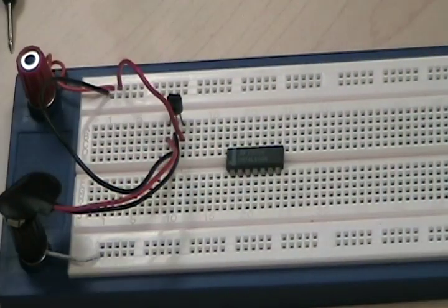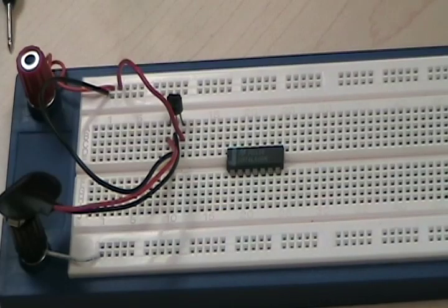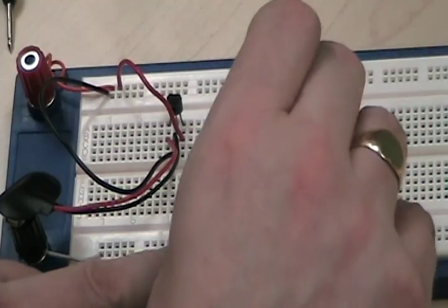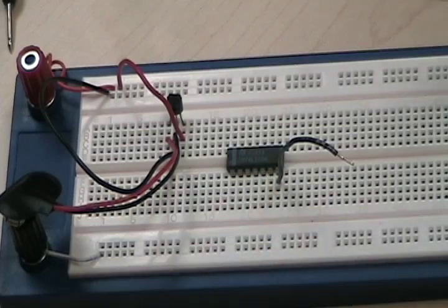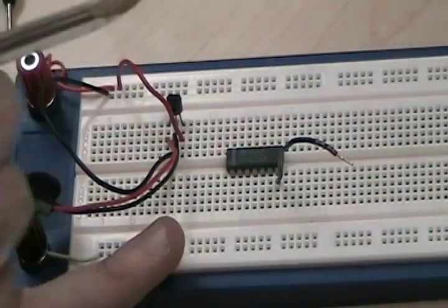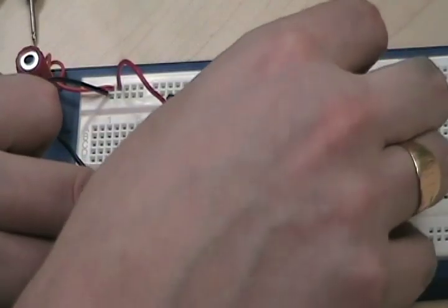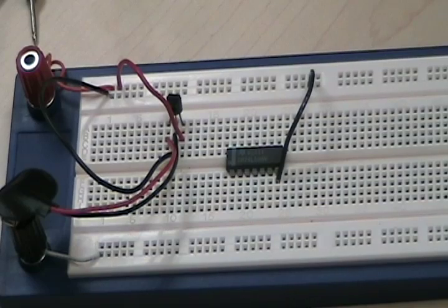So we want to take a black wire. You don't have to use a black wire, but it's just a nice thing to do. It's nice to know what's connected to where. And pin 7 on here, of course, is right here. Remember, we're looking at it. Pin 1, pin 7, far right. Top right is pin 8, and top left is pin 14. So we're going to bring it up to our ground line from the top. We're going to ground it. That's step 1.